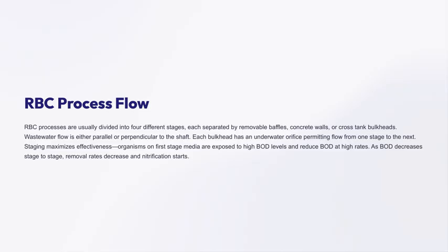In the first stage, the media is exposed to high BOD levels, meaning the organisms here work vigorously to reduce BOD at a high rate. As the wastewater progresses through subsequent stages, the BOD levels decrease. This naturally causes a drop in removal rates, but it's also where nitrification begins to take over. This staged setup is key to optimizing overall treatment efficiency, aligning perfectly with our goal of understanding how biological treatment processes are designed for maximum performance.